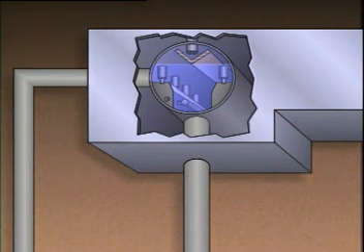In the opposite case, the boiler drum water level would rise. In a short time, this excess water would be carried out of the boiler drum, along with the steam, to where it could damage components such as the boiler superheaters. Damage from mismatched steam and water flows can be prevented by controlling the flow of steam entering the turbine and the flow of feed water to the boiler.